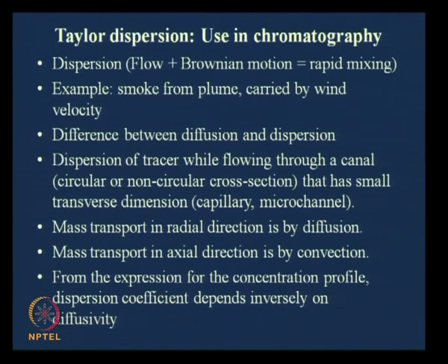Next topic that I pick up now is known as Taylor dispersion. Remember when we were talking about that on off mode of mixing, there, instead of a diffusion coefficient, I mentioned dispersion coefficient, and instead of D I have written D star. There is a reason for it. When we talked about a spot of tracer diffusing into an infinite medium, we restricted ourselves to diffusion coefficient. However, when there is a flow as well as diffusion, then we have to take some additional terms, and then we call this process dispersion rather than diffusion.